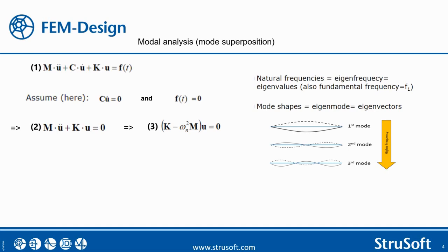Eigenanalysis is used to determine the basic dynamic characteristic of a structure. The result of an eigenvalue analysis indicate the frequencies and the shapes at which a structure naturally tends to vibrate. Although the result of an eigenvalue analysis are not based on a specific loading, they can be used to predict the effect of applying various dynamic loads.